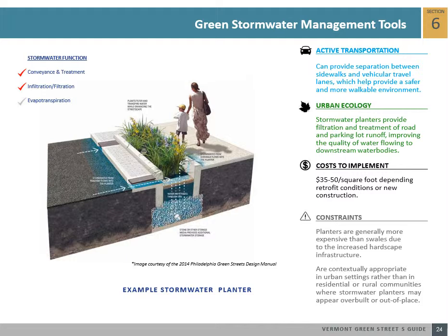Suspended pavements and structural soils give support to pavement while allowing roots to move through an extensive and loose soil profile. Suspended pavement systems utilize an underground scaffolding to support the weight of infrastructure without compacting soils. Engineered structural soils combine stone, soil, and a binding agent to hold the soil to the stones. This provides a similar service to suspended pavements without a rigid scaffolding. Structural soils support pavement while allowing tree roots to move through pore spaces.